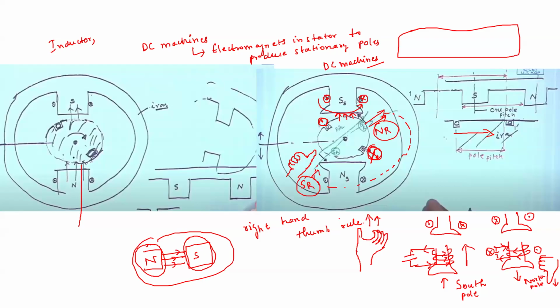if you use a permanent magnet machine, it is generally smaller in size compared to the electromagnet configuration. So if you have space constraints or maintenance constraints, like your machine is located in such a location where you cannot do too much maintenance, then in such special cases generally permanent magnets are used. But in most industrial cases we use electromagnets only.